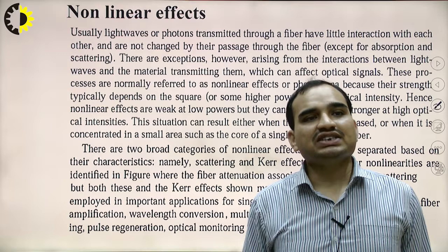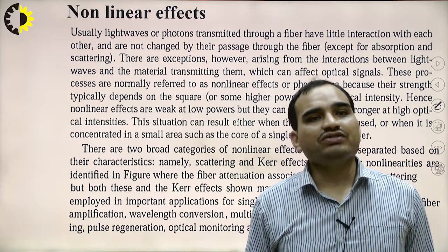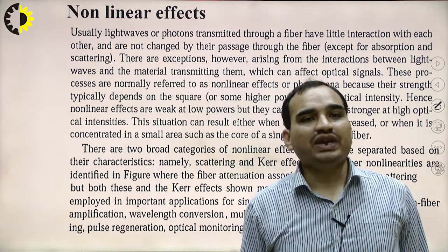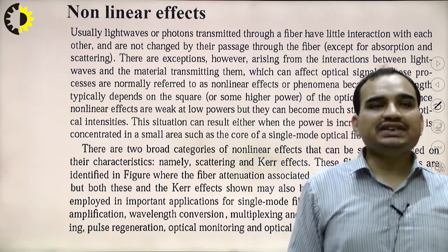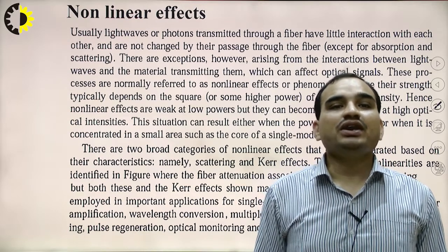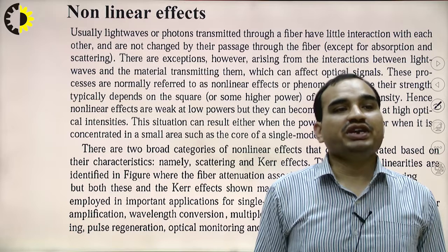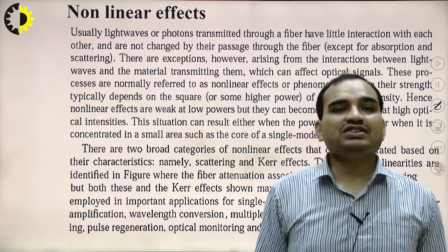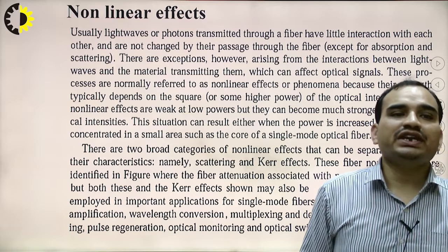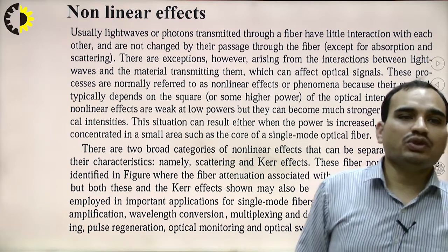These processes are normally referred to as nonlinear effects or phenomena because their strength typically depends on the square of the optical intensity. Hence, the nonlinear effects are weak at low powers, but they can become much stronger at high optical intensities. This situation can result from the power being concentrated in a small area such as the core of the single mode optical fiber.